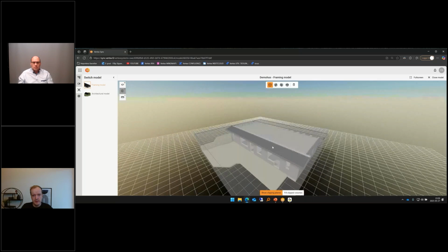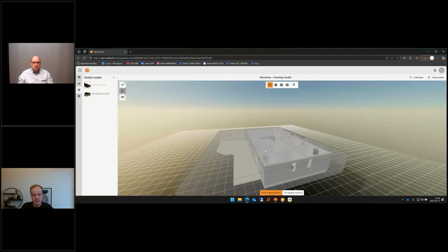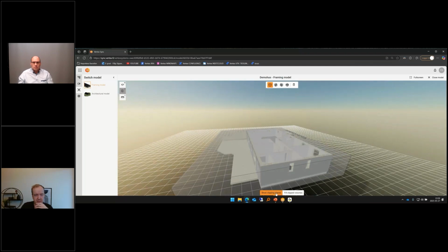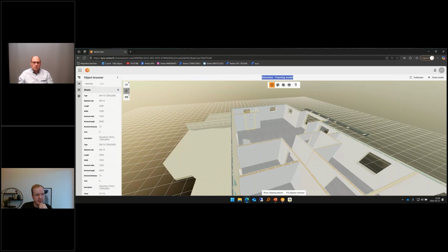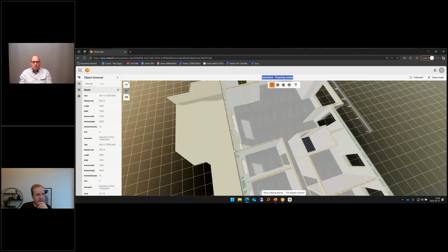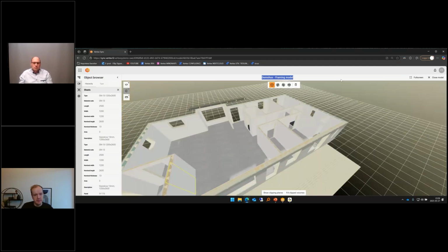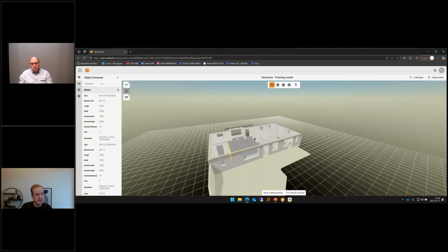And then if I go down here, you will now see if I select the sheet, I can get information regarding that sheet. This is useful for someone who's maybe at the building site or a customer who needs to verify that the information is correct. I can here mark a sheet and then click the information, and here it says it's a gypsum sheet. It's 13 millimeters and it's 1200 by 2600. And that works, of course, on any piece or any sheet or anything really. It's nothing really that stops you. So a very useful tool both for the building site and for production or sales.